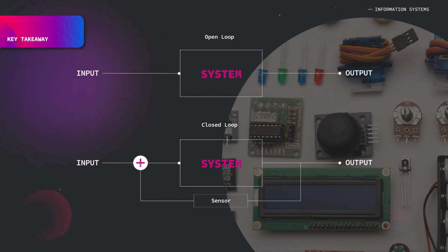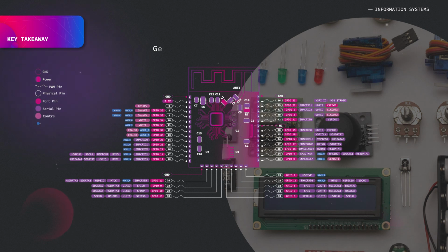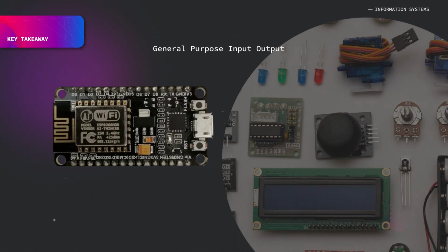To control actions and receive feedback, controllers and microcontrollers, which are small computers with GPIO, can be programmed accordingly. The only limit is the technical specification of pins. To simplify development and experimentation, a development board can be preferred over a microcontroller chip, as it simplifies power supply, voltage tolerance on pins, programming connector, and USB.